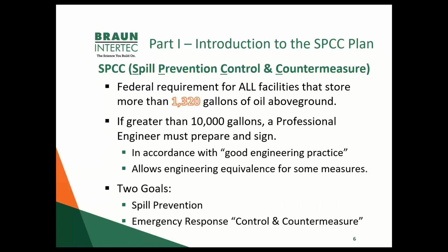So the SPCC plan. The SPCC stands for Spill Prevention, Control, and Countermeasures. In short, it is a federal requirement that applies to all facilities that store more than 1,320 gallons of oil in above ground tanks and storage containers. Note that if you have more than 10,000 gallons, your SPCC plan has to be prepared and signed by a professional engineer.